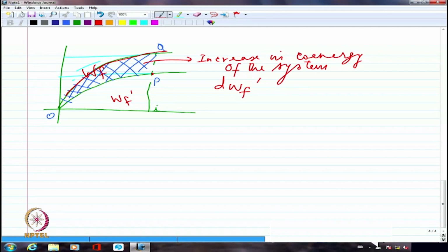Is this clear? With sinusoidal excitation, there is nothing like a constant value, never ever. RMS values are constants, yes, fine, once it reaches steady state. We basically have the flux changing, and reluctance is also changing. So MMF can remain a constant. You look at it that way. Flux is changing. It has gone from lambda 1 to lambda 2. Please note that.